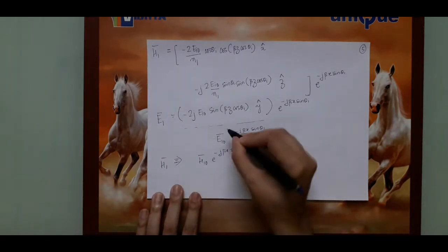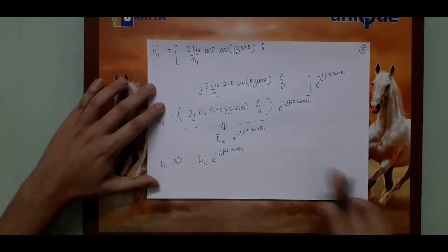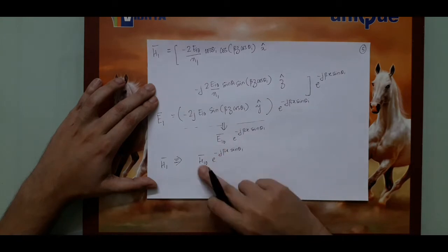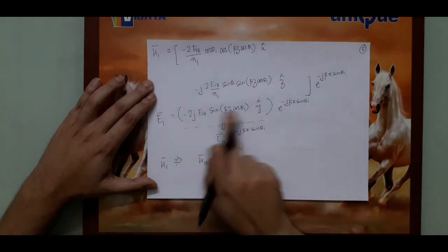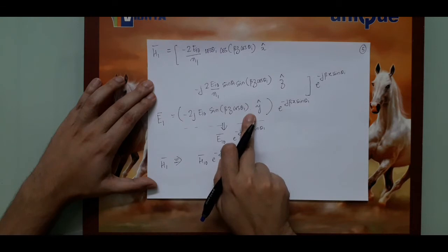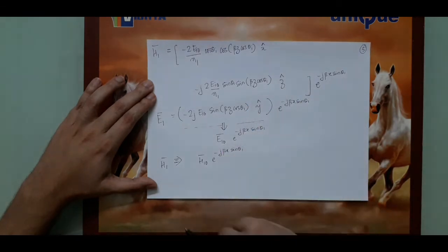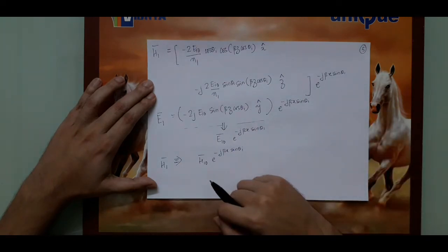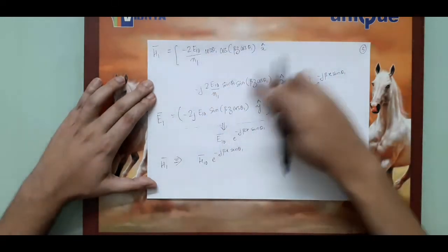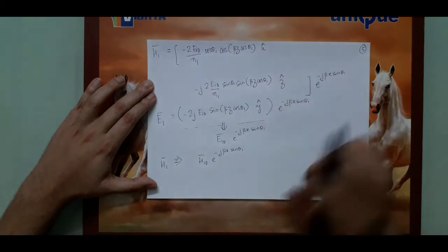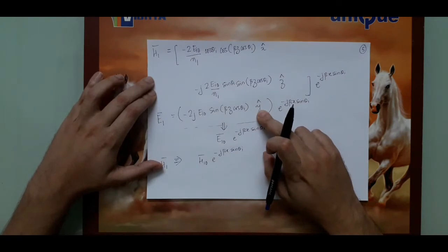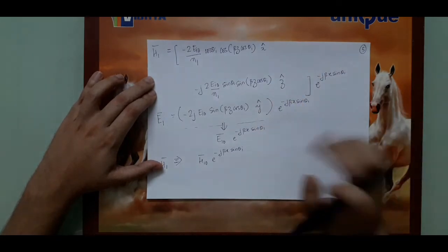So this becomes equivalent to this. Now again, let us observe the nature of E10 and H10. So E10 is a vector obviously, but existing along the y direction. So therefore, this is a vertically polarized field. And the H exists along the x and z axis, which makes the E and H vectors perpendicular to each other or orthogonal to each other.